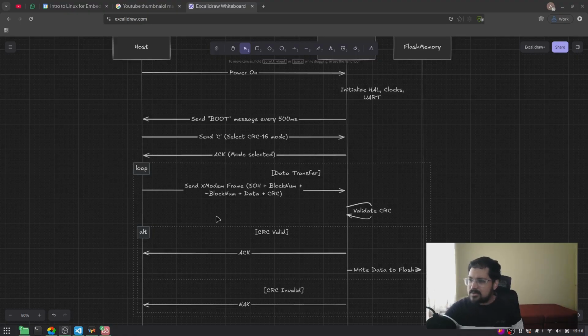Now CRC is used in protocols to ensure data integrity, which means that during this transmission over the wire, you don't have any bit flips happening. Now the CRC at most can handle 1 or 2 bit flips, but it's still a useful tool. Modern algorithms use AES-CMAC, or cipher-based message authentication codes. Now that's a big thing. But for a short wire distance, and if you are okay with retrying, this CRC method works well enough.